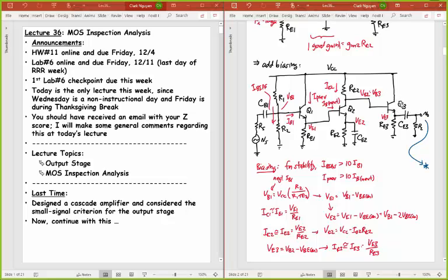Everything is okay from a small signal sense because the voltage you're dropping across the base emitter is still very small compared to the thermal voltage, 25 millivolts. And you could say the same thing for Q2 as well. In fact, if this is an emitter follower, which you've learned already, then it's got a gain of 1, which means if you're swinging 2 volts peak to peak out here, you've got to be swinging 2 volts peak to peak here, which is the output of this stage Q2.